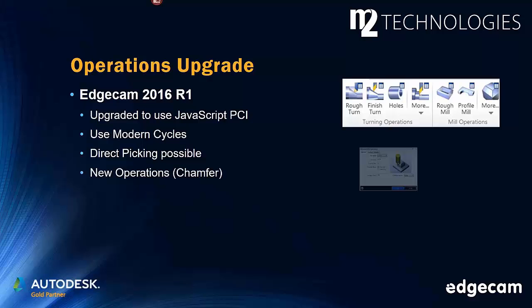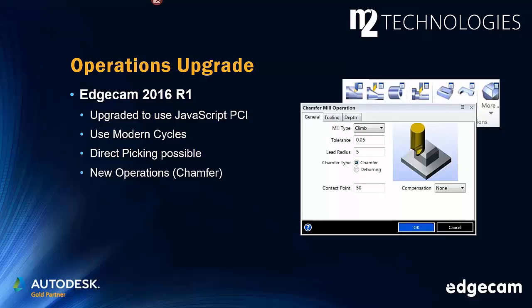So what we mean by that is, for example, chamfering. Chamfering used to use the older method of doing things where the profiling cycle was used. But there is a new chamfer cycle that's been offered in the software a few versions back that makes chamfering much easier to pull off than the way that the profiling did it. The new chamfering operation uses the new chamfer milling cycle instead of the profiling method.